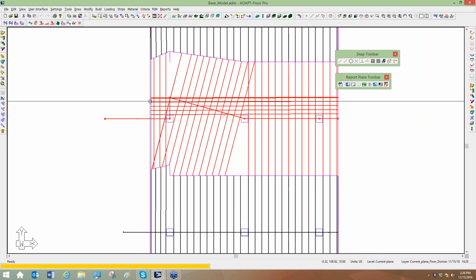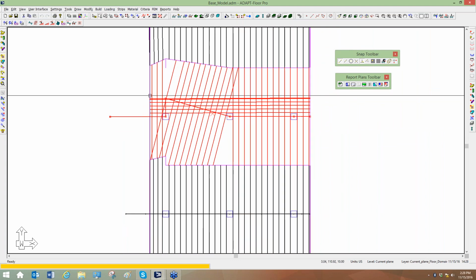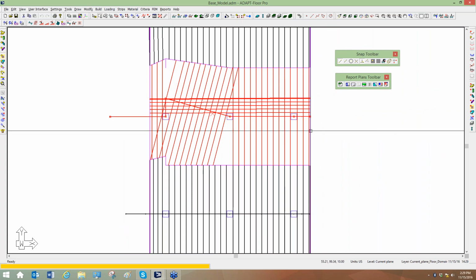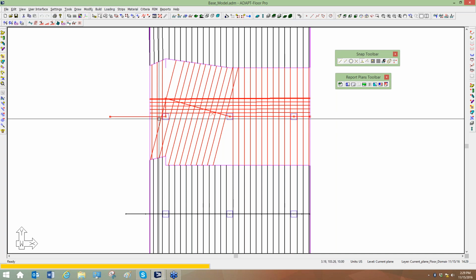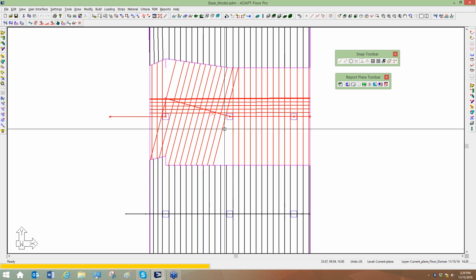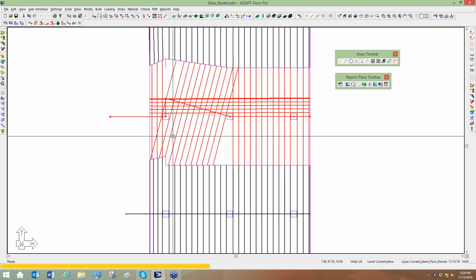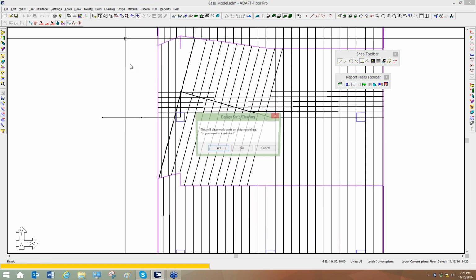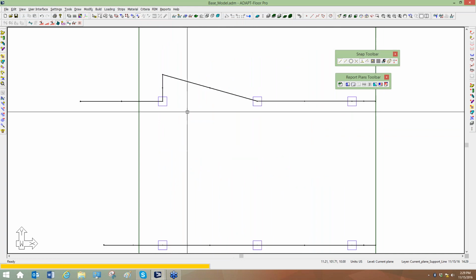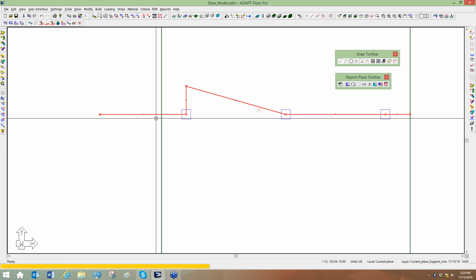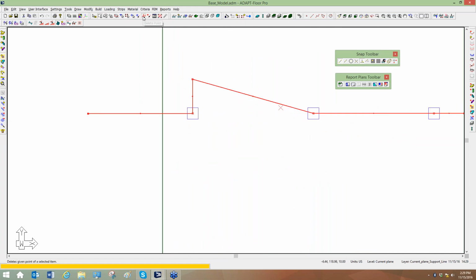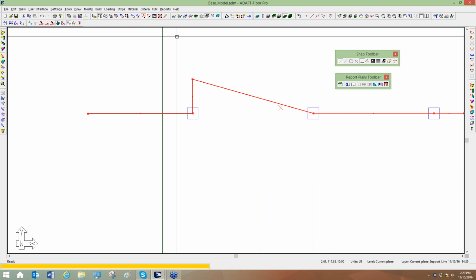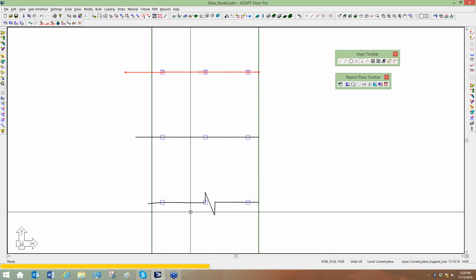And you can see those integrate all across the slab because there's no boundary to stop them. It goes from edge of slab all the way to edge of slab. And these really should be assigned to Y direction strips. So if you have that type of mistake in your input, you can always select the support line, go to this option to delete a point, or you can add a point if you needed to add one, and I can just delete this point.